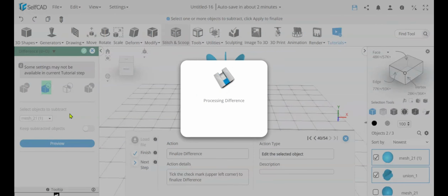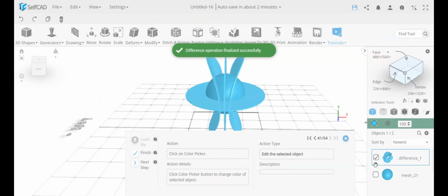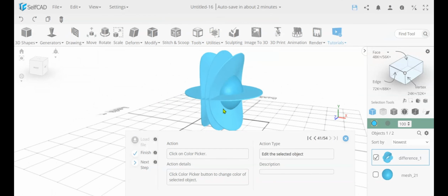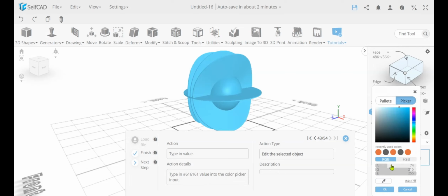I'm going to remove the cylinder. What's happening over here is that when you remove the cylinder, you can see it from the image, I can't hide this and show it in the tutorial, but you have the hole made inside this. This piece is already cut out, and it's cut out with a hole where the inside circumference is just 98, which means it leaves it a little bit deeper in, because if I removed a 98, a smaller sphere, meaning if this sphere is 100, it will stick in just 2 into this sphere.